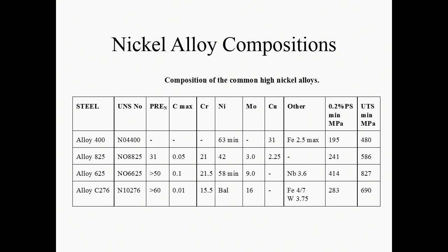It can be used for cladding, but it's sometimes more in fittings that you'll encounter that. Not quite so good properties, but not that bad either. So they're better than austenitic stainless steels, but they're not as good as duplex steels in terms of strength. But they're very much more corrosion resistant. You can put boiling sulfuric acid into these materials, and it won't go through.